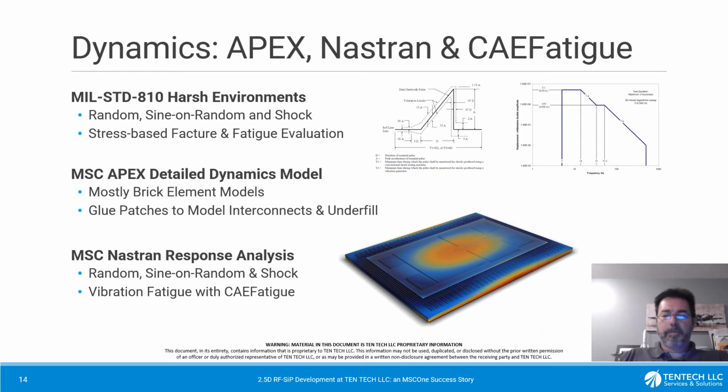So once we're happy with the thermal design, we unfortunately have to go to dynamics. And dynamics is where all those pretty and neat electronic systems and solder balls and components get really in trouble. This happens often, particularly random vibration in harsh environment. This is typically a fatigue problem, so we have to pay close attention to that.